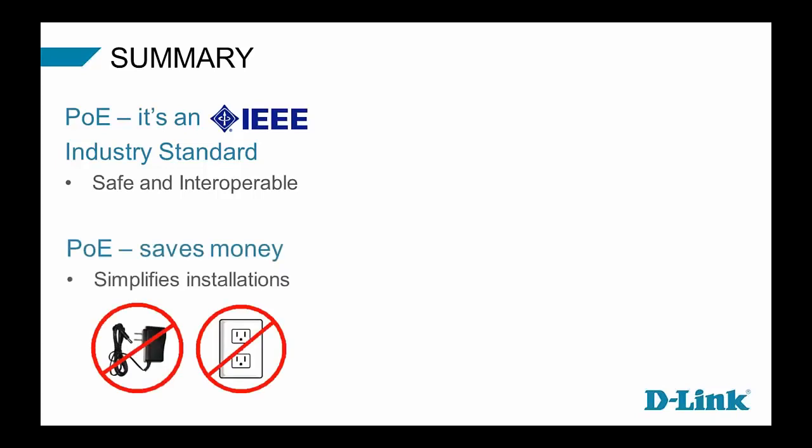We talked about the benefits of PoE: saves money, minimizes cable clutter, no need for AC to DC power adapters, no need to have electricians come out and install AC power drops because PoE is considered a low voltage application.